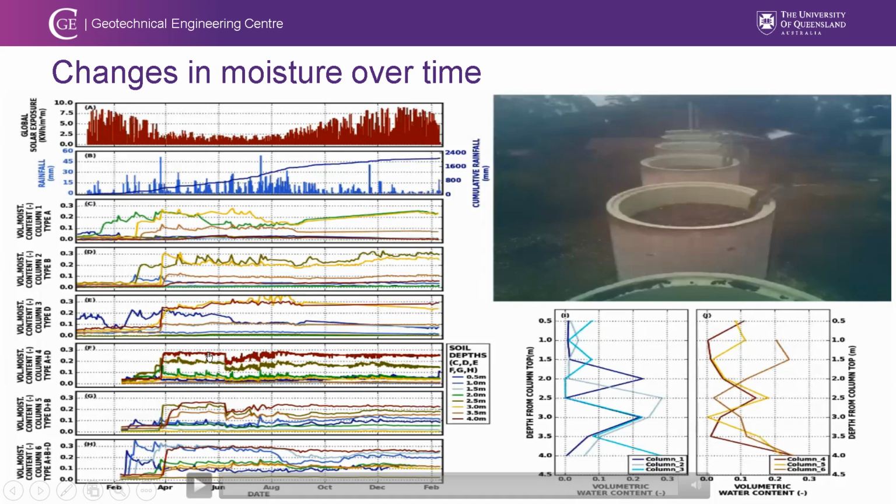During the stabilization process, we also see that some of the locations have a slight decrease of moisture content. That is actually because of gravity drainage, because we could imagine that the flow is not actually 1D within those columns. There is a wetting front, which is basically the preferential path, and later on the preferential path will expand. That will allow the flow to go through quicker as compared to before, which could help drain the local moisture down to the bottom, which is the reason why we could have a sudden decrease of the moisture content.